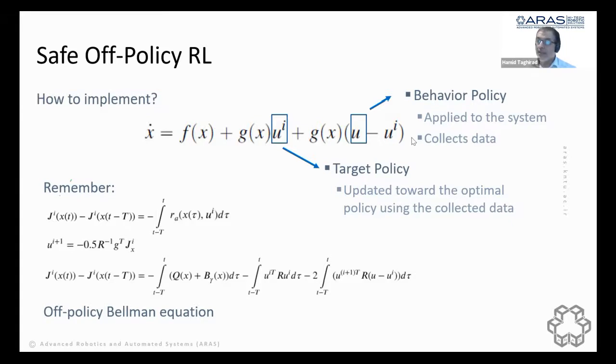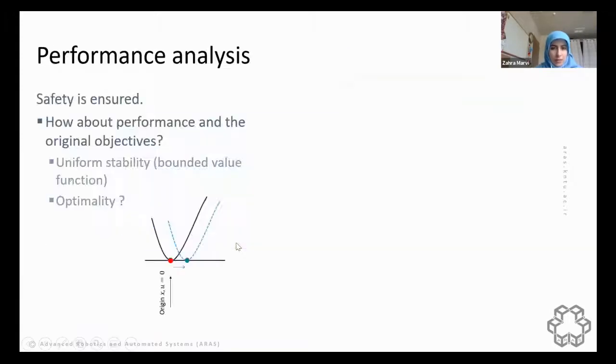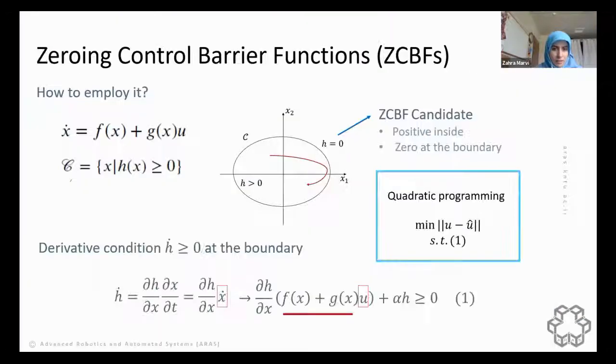There is another question regarding your talk. Can we use this BLF for output constraints? I mean, if we have y equal to Cx, a combination of states, can we also include that constraint in the BLF? Yes, if you can represent it as some inequality constraint, it's a general form. It just needs to be a smooth function. It can be a function or combination of states. Yes, you can do that. Perfect.